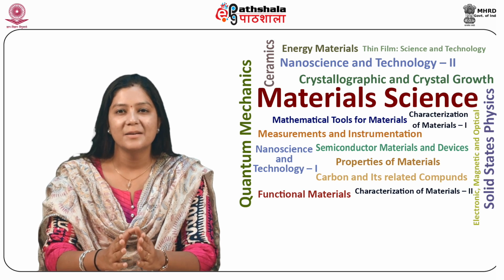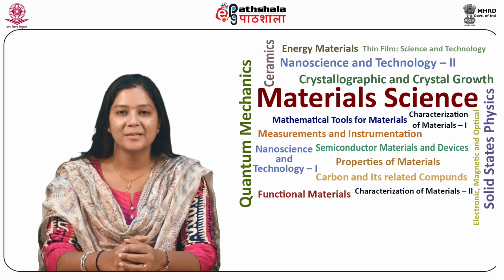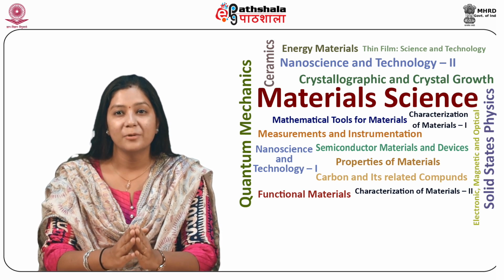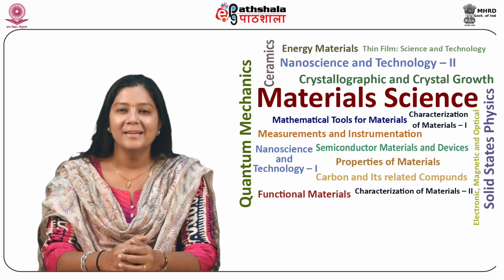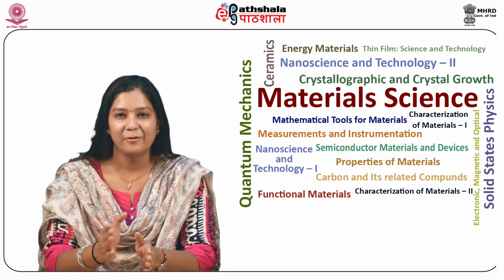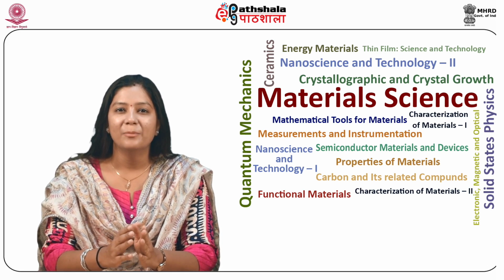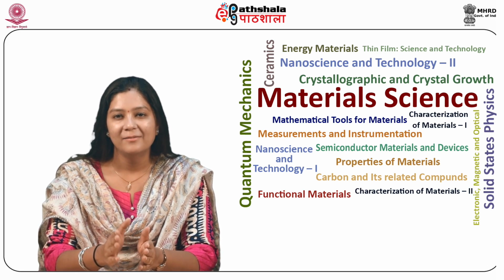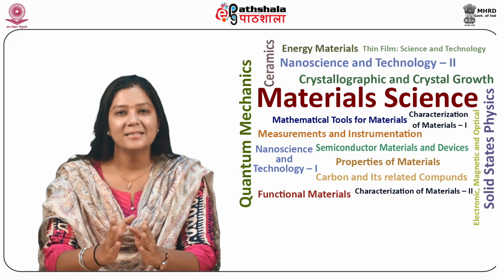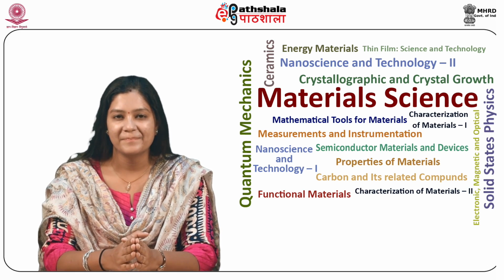So etching is a process used extensively in the microfabrication process. Etching includes all the techniques which are aimed at uniform removal of material from the surface of a wafer. It is mostly used in parallel with the lithography process and is used to cut open the protective film on the surface.